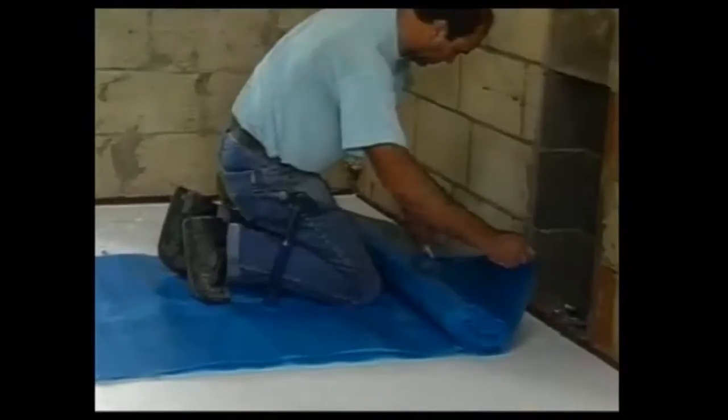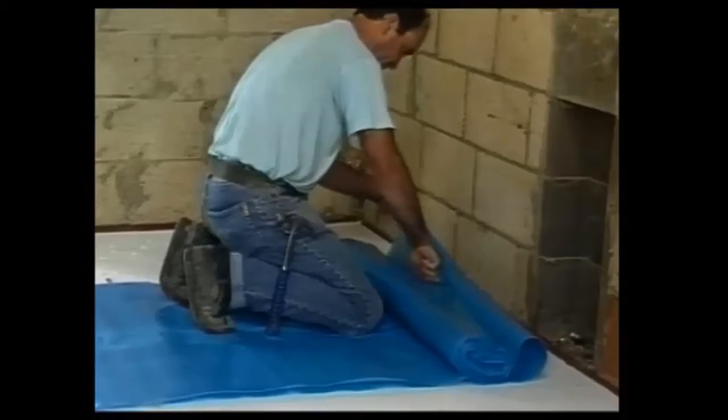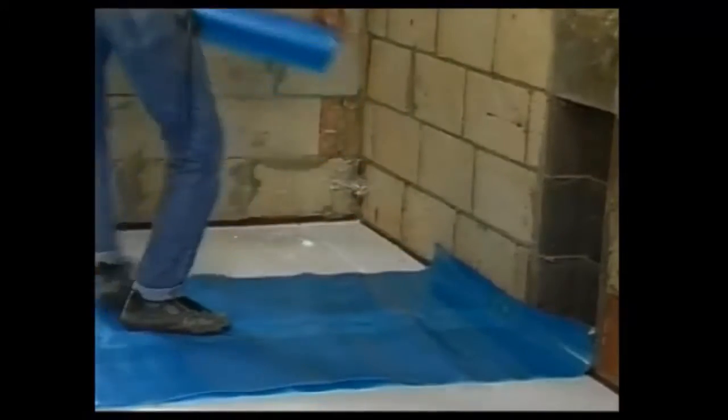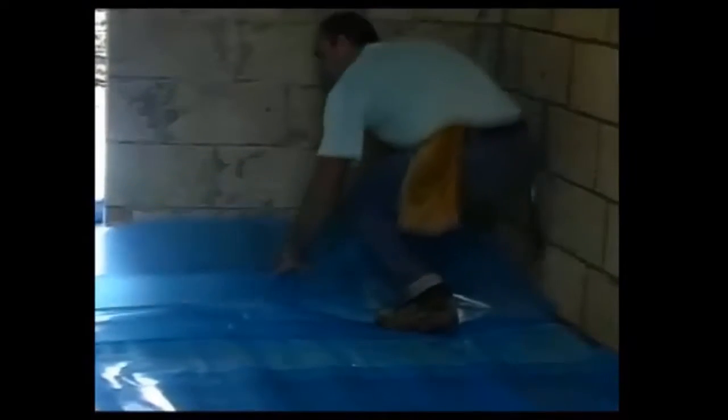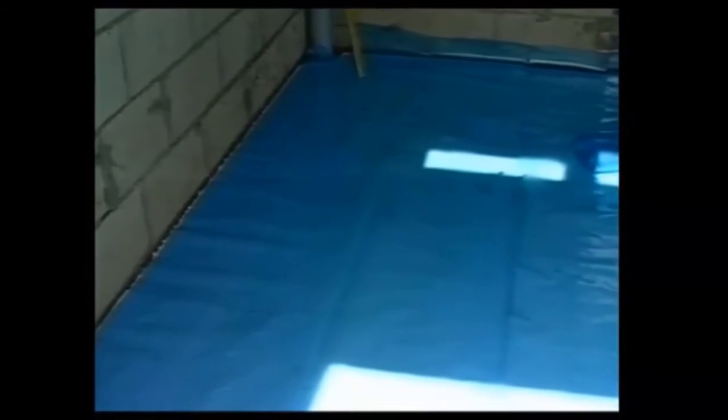Chipboard is very sensitive to moisture, and in damp conditions the boards can swell and disintegrate. To prevent moisture from the drying floor structure affecting the chipboard, a vapour check is usually required immediately below the board. This is in addition to the damp-proof membrane below the slab. To ensure the vapour check is continuous, it should have taped joints. In situations where the main DPM is above the floor slab, this additional vapour check is not required.